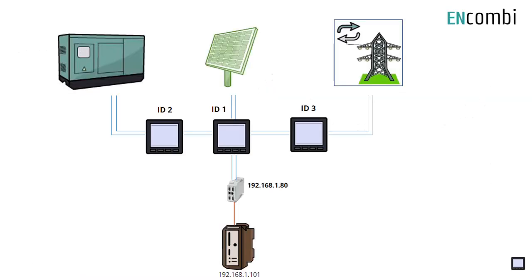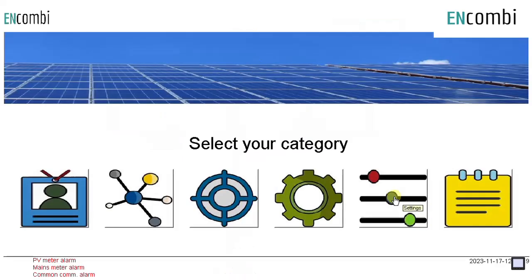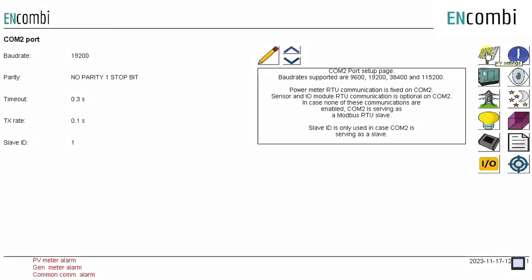In case of interfacing with Modbus TCP to Modbus RTU meters via a TCP RTU converter, the converter setting must be enabled. The IP address is to be set equal to the converter, and the Modbus IDs are used in the TCP frames from the ECPv2 for identifying the individual meters. Let's see how to do the setting for this kind of installation.